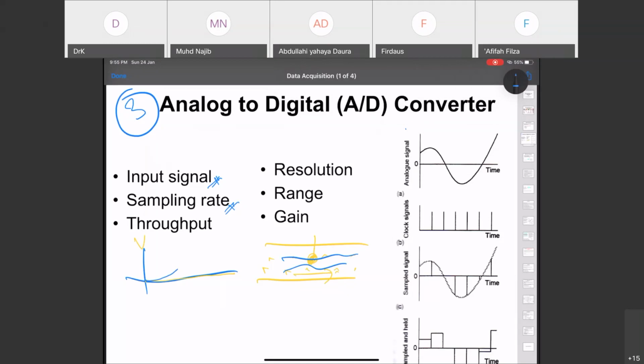How much it goes up depends on the operating voltage of that sensor, of that signal conditioner. If the signal conditioner is working at a maximum of 12 volt, the information from the sensors that comes into your system will go up to at most 12 volt.